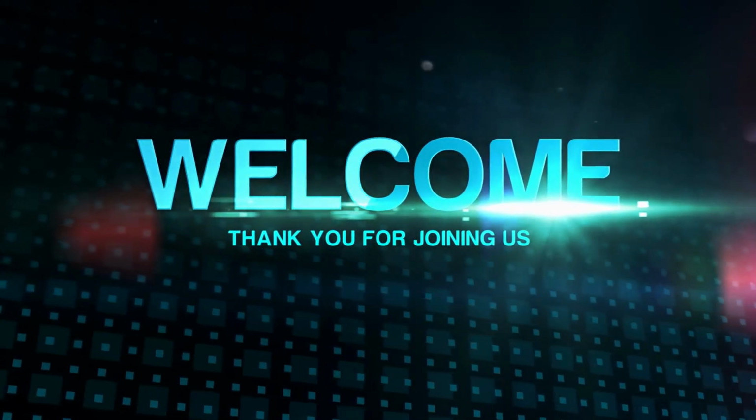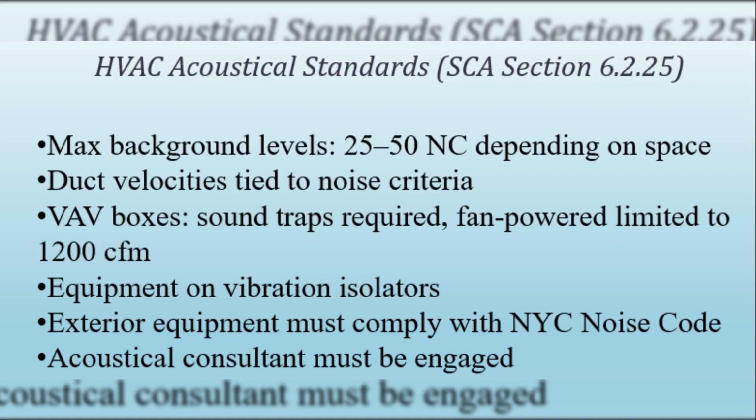Let's get started. The standard sets maximum permissible background sound levels, measured in both dBA and NC values. For example, classrooms must not exceed 40 dBA or NC 35, while music rooms and auditoriums must be even quieter, at 30 dBA or NC 25. Spaces like cafeterias and kitchens are allowed higher levels, up to 50 to 55 dBA, because of their function and equipment use. It's important to note that these background limits only apply to continuous mechanical noise from HVAC systems. Transient sounds like traffic or aircraft are excluded from this requirement.